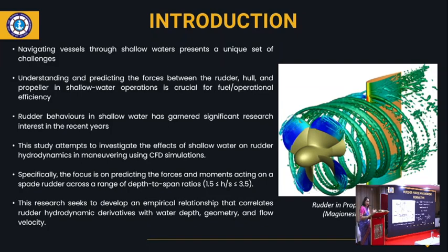Of course, opposite to the direction of flow we have drag, and in the perpendicular direction we have the lift. And this is how Y delta, the rudder force, is determined theoretically. To make the problem simpler, it is understood that the rudder moment derivative N delta can be a function of Y delta. So we further narrow our focus to Y delta, that is the rudder force derivative, which makes the study a little simpler.